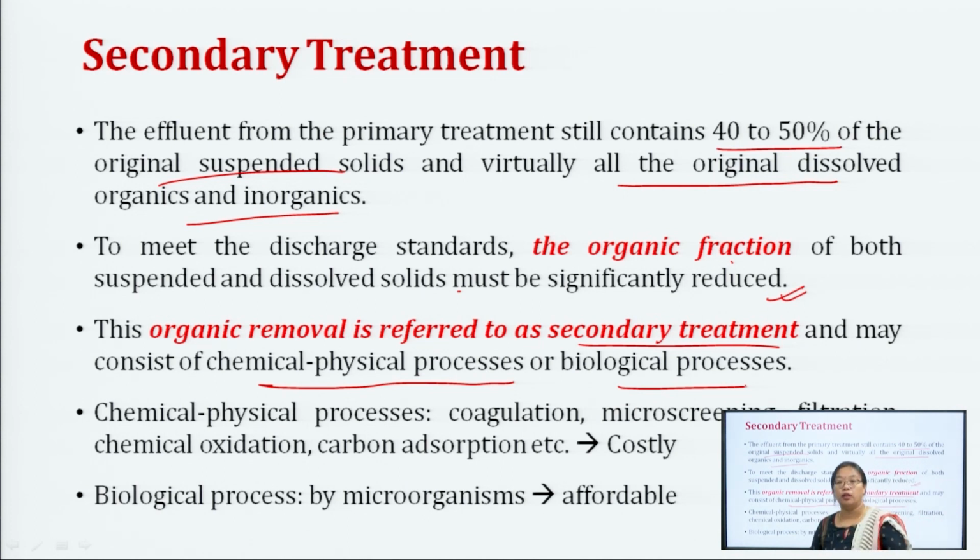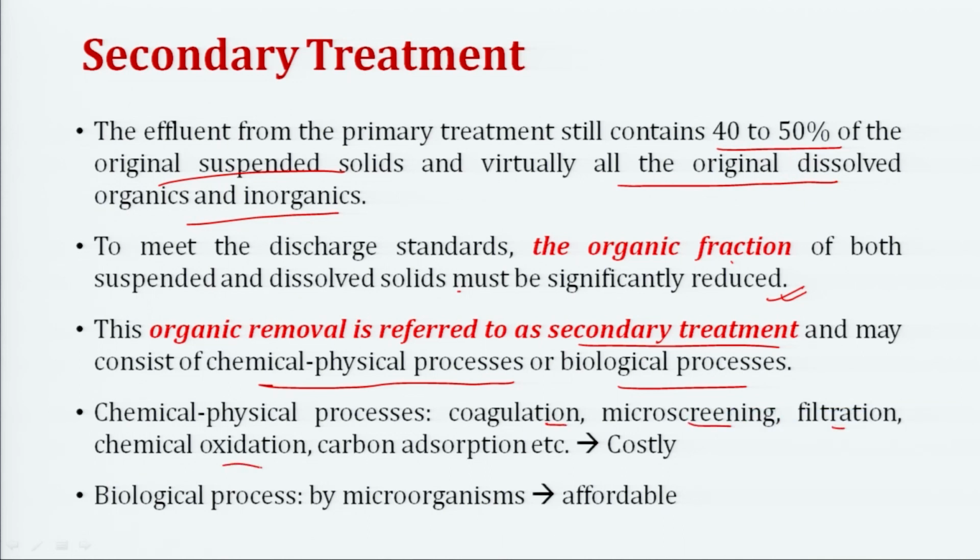So, secondary treatment comes after the plain sedimentation, right. It is supposed to remove most of the organic fraction, and it consists of either chemical or physical processes or biological processes. The chemical physical processes may be coagulation, microscreening, filtration, chemical oxidation, carbon adsorption, etc. There are many things by which we can do it, but we do not generally use them.